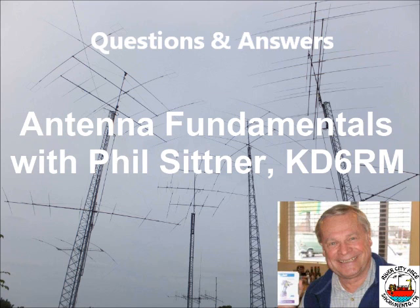But what we'll be able to do is change the resonant frequency of the antenna by changing that ratio of capacitance to inductance. The way you do that in a dipole antenna is you make it longer or you make it shorter. That's all you do. It does exactly the same thing that I'm going to demonstrate here.